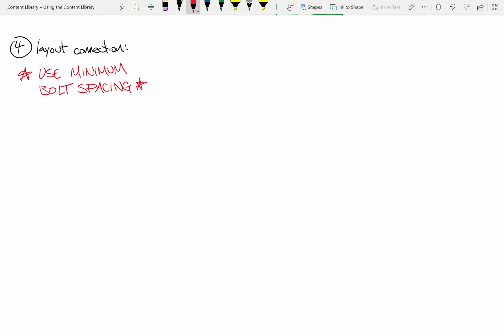Okay. So let's see what we can see. All right. So first off, we need a minimum edge distance and we need an S min. Now S min's pretty easy. How do we compute S min? Let's do S min first. 8/3 of the bolt diameter.